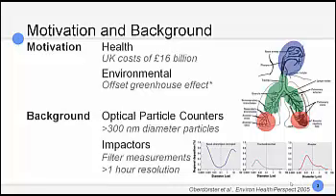And then the other side are the impactors. And they are quite classically used within the environmental standpoint as well as pharmaceuticals. But their main limitation is that you need to use filter measurements that usually last for about an hour plus, so you lose any of that time resolution that you'd like. And so that's where the resonators come into play, where we'd hope they have a high sensitivity so we can measure those small particles, and they also give us the time resolution we'd like.